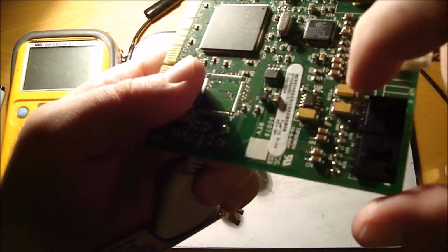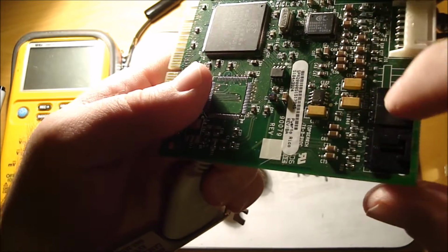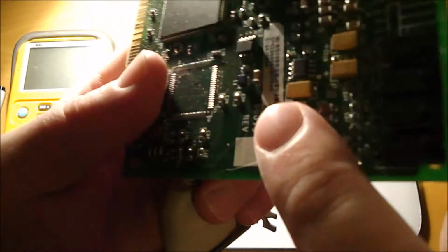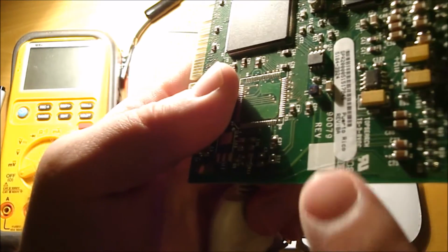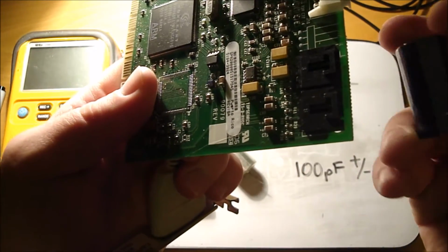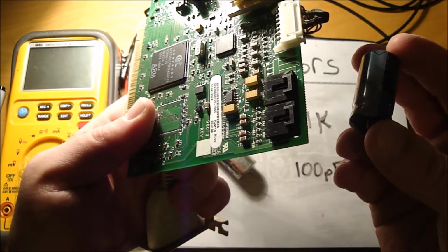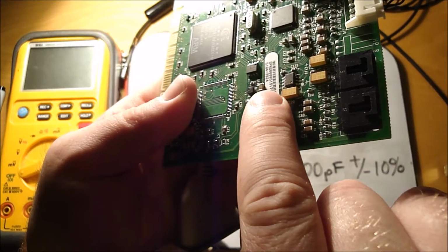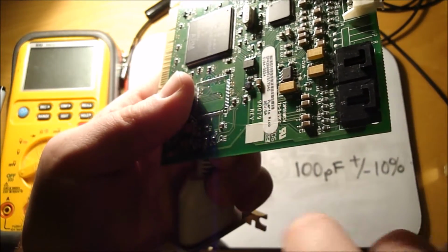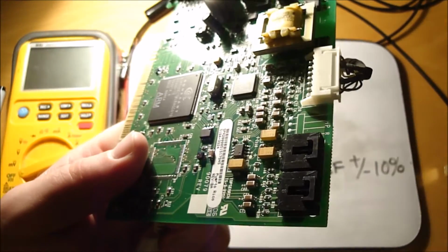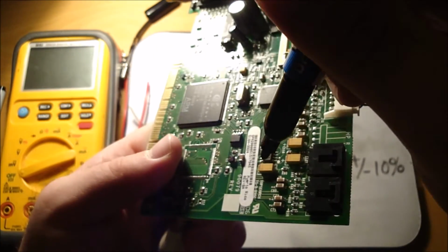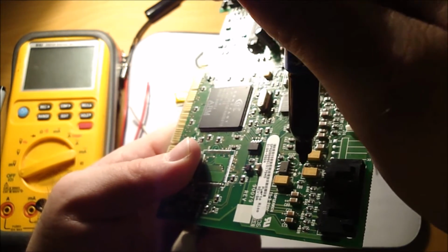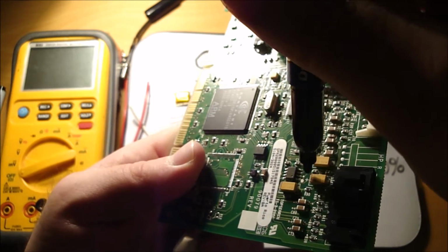You have these big yellow rectangle capacitors right here, these three, and you can see the dark stripe on one side of the capacitor, and contrary to these big cylinder type capacitors, on these surface mount rectangle ones, the dark stripe actually marks the positive side. And the way I know that is because the board actually has a plus sign there showing that that's the positive side, and right there is the stripe, and there's a positive sign.